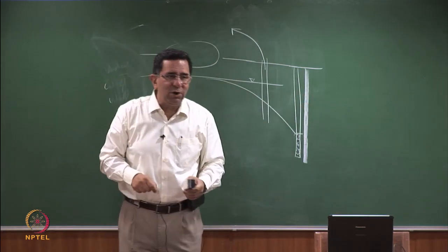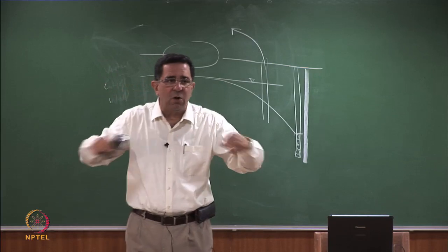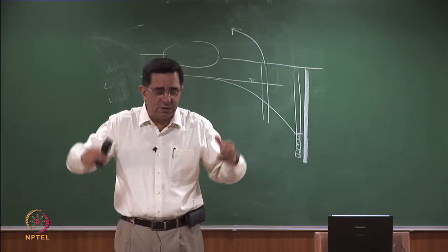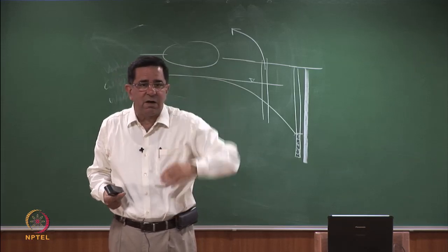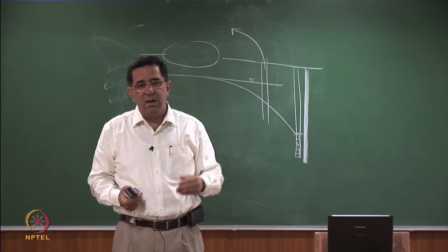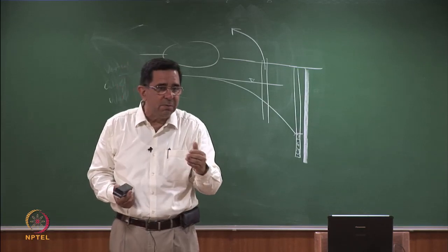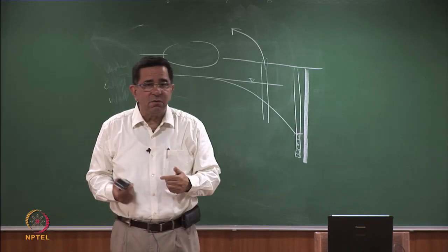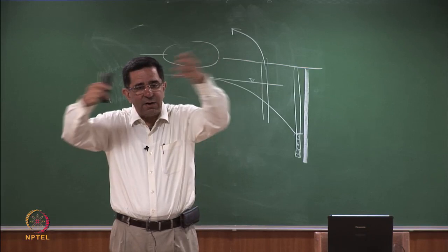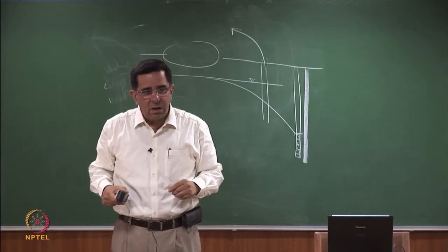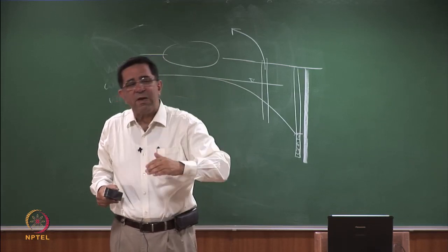So the design is not only of drawdown, it's also of injection wells. So when you do the design, the question that is being asked is that when we do all this pump and treat, or when we do the subsurface drainage, the water is taken out, then because of increase in effective stresses, settlements will occur at the surface. Answer is yes, they will occur. The question is, do we do very massive drawdowns? The answer is no, we do limited drawdowns. However, in the next lecture we will see we also put injection wells simultaneously. That means water is being extracted, treated and injected back. So you try to keep the level of the groundwater table about the same as what it was originally, or the drawdown may be very limited.